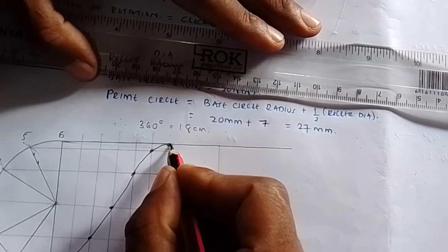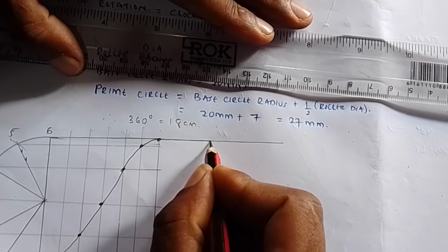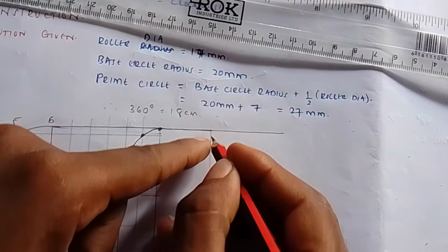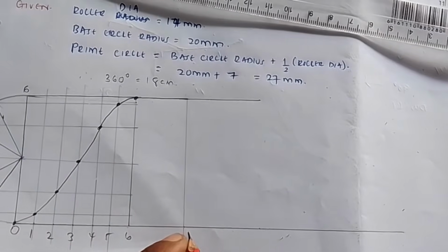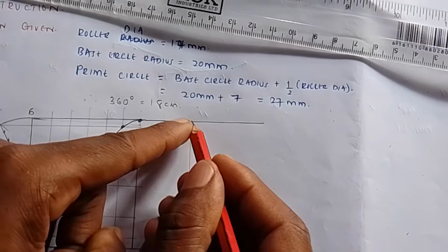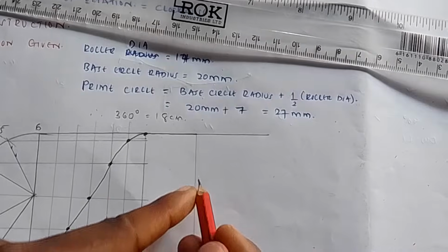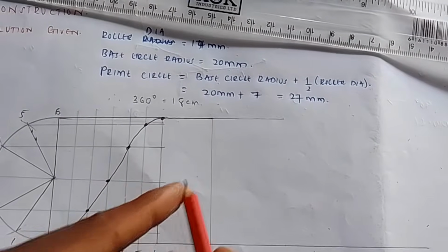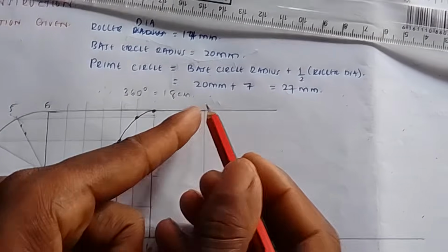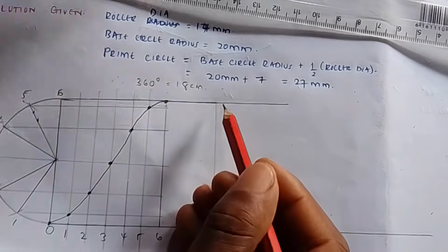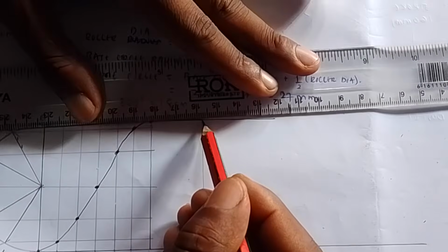If it's a fall, and our dwell was at this particular point, from this point it is falling 20 downwards. You don't start from down to measure 20. You start from up. It is falling. If you are told it is rising further, then you will start from that point and go further. But it is falling from this point. So it means from this 60, you go downwards 20.